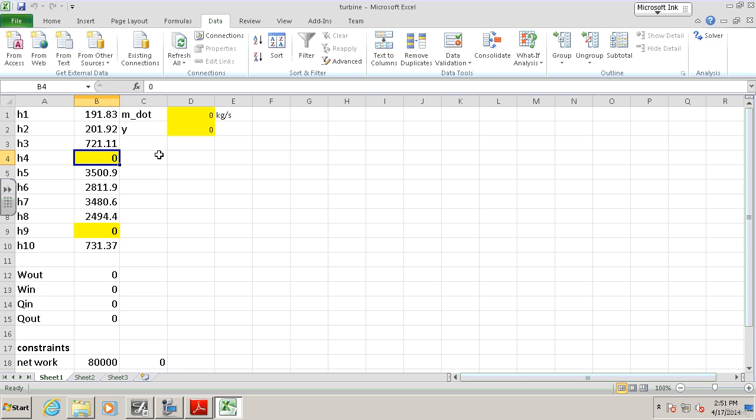So what I had to do with H4 is I said, you know what? H4, H9, H10, they're all pretty darn close. So I just put in there 725 for each one, just to start it, just an initial guess on both of those, right? Could you get away with 1? No, probably not. And then here's the key one, M dot.